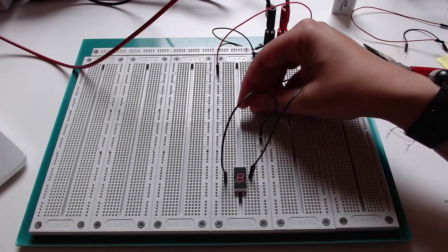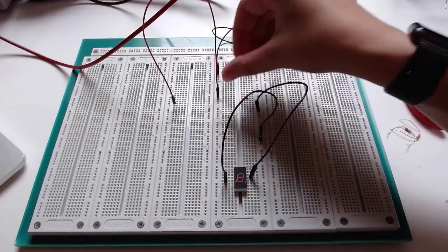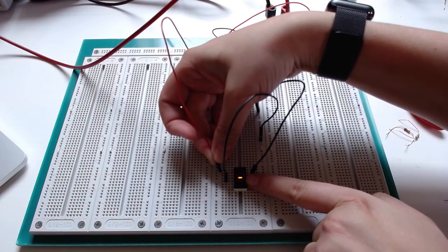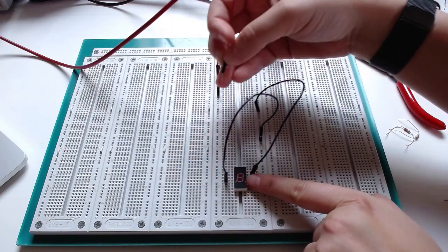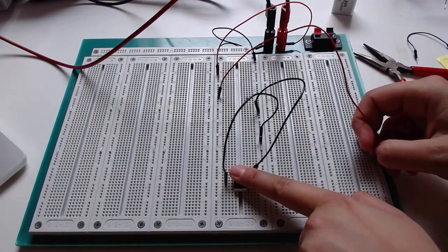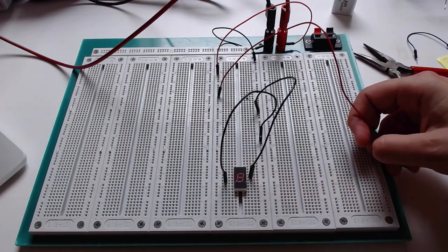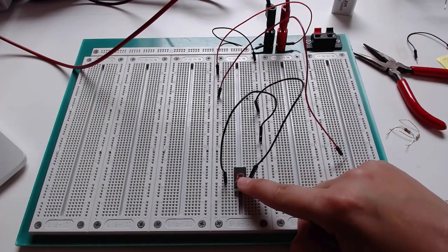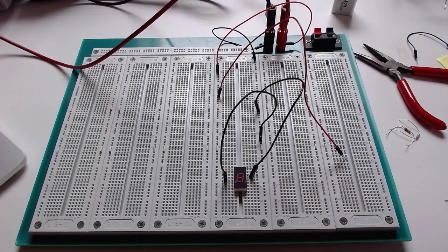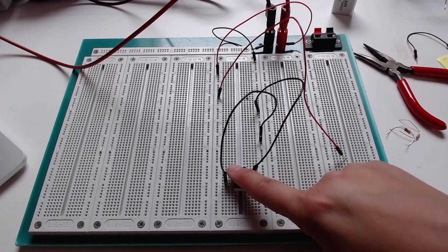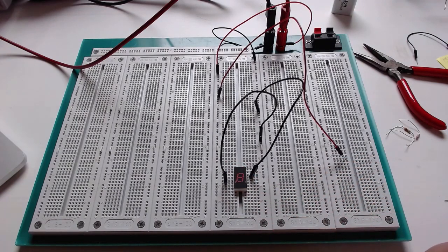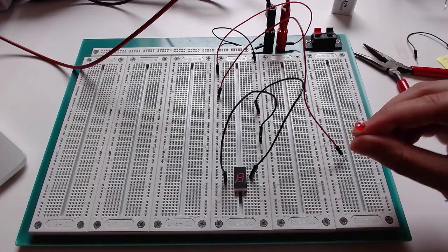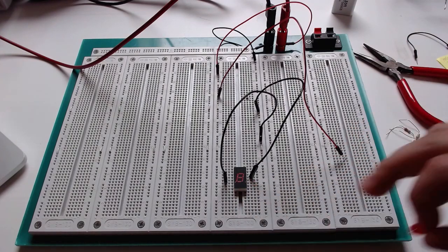Now, if I were to do direct connections to 5 volts on any one of these, you can kind of see that the LED has this orange glow. Orange glow is pretty bad, and if I stick my finger over the display, I actually notice that it physically heats up. So those LEDs that are on with that direct connection to 5 volts get physically warm. Now that's a problem, right? Because that warmness means that eventually things are going to overheat and I'm going to wind up with this kind of a situation, which we don't want to happen.